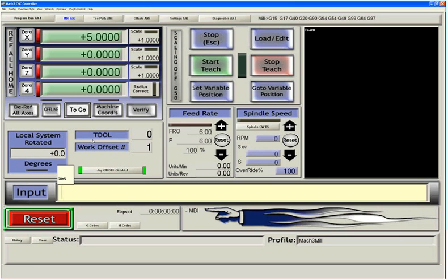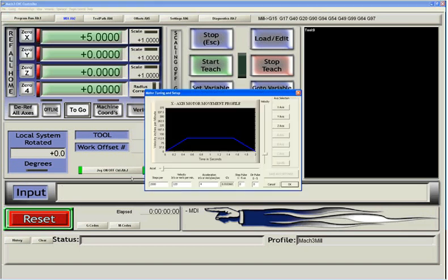This is all set up by the motor tuning steps per inch. And if we go up here and bring up motor tuning, you can see that for each axis there is a steps per. This needs to be set to the number of steps the system needs to send out to move your axes that amount, 1 millimeter or 1 inch, depending on the selection that you have selected for the system. The acceleration and the velocity you should set to a comfortable level prior to doing anything, and hit Save Axes for each axis. You can then adjust your steps per inch to make the system accurate.